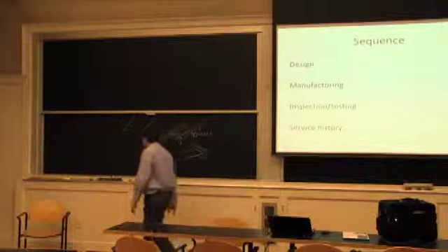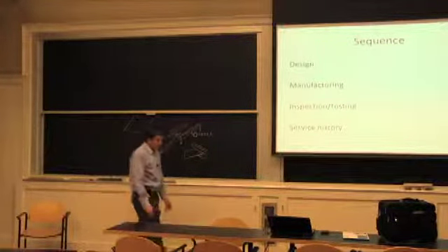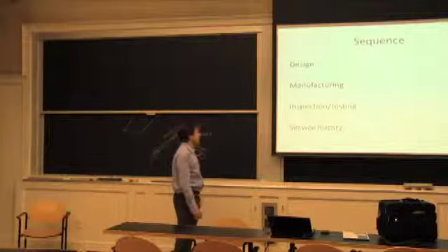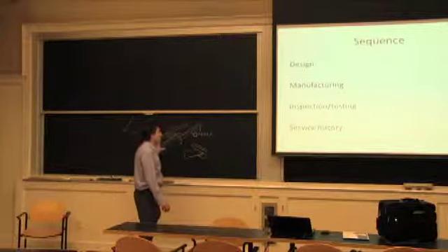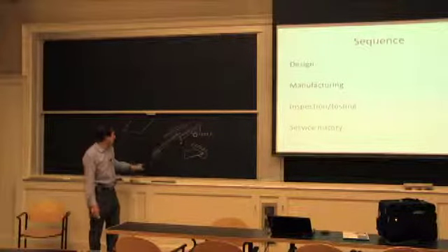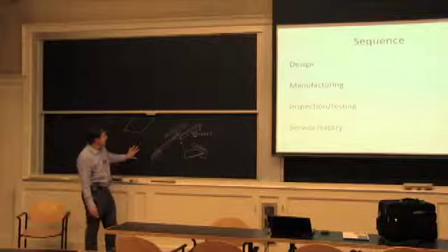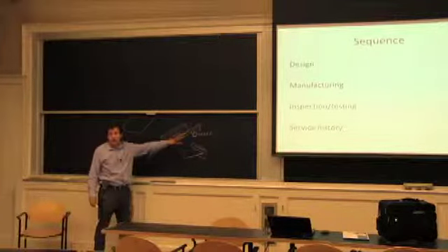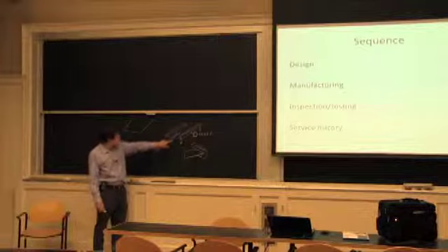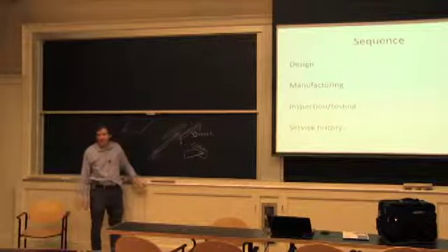So in terms of looking at what could happen in a process, I'm taking the trailer example again. If this was going to be built by somebody else after I came up with this design, I have to be very clear that there can't be any welds where I decided there was not going to be any tension weld.